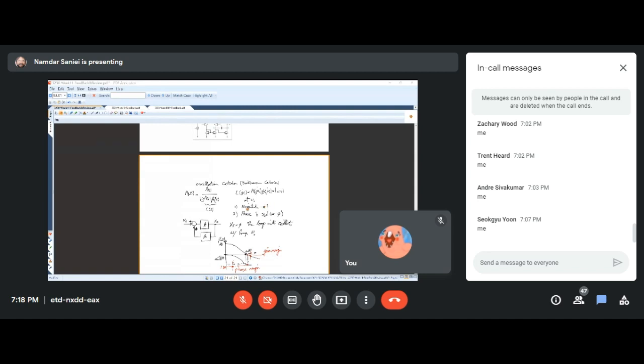Okay, and if at the same time we have a 360 degrees phase difference, then we will oscillate. The circuit will oscillate, even if there is no input on it. So even if we turn off the input, this positive feedback causes an oscillation.